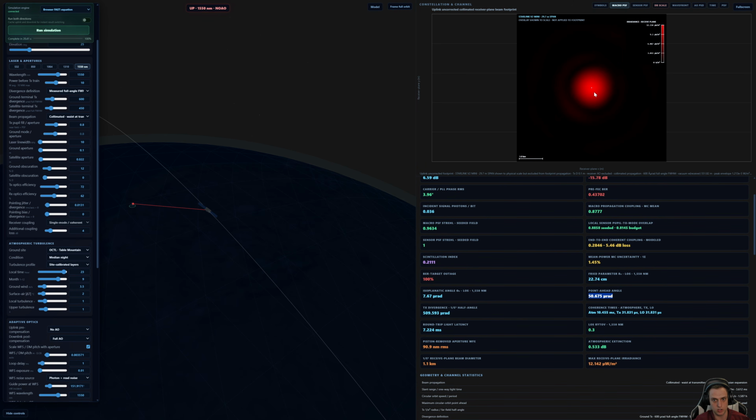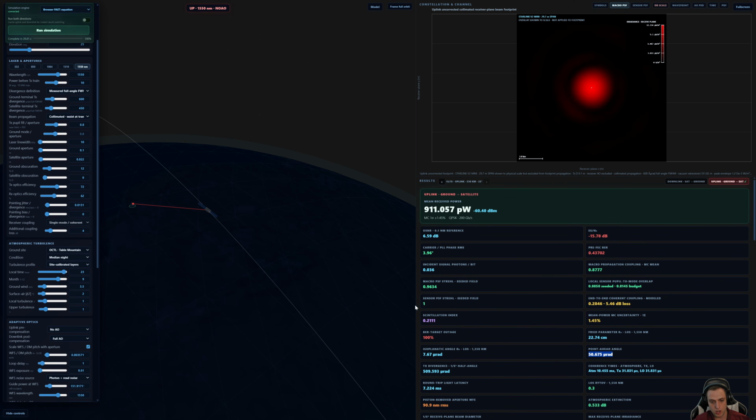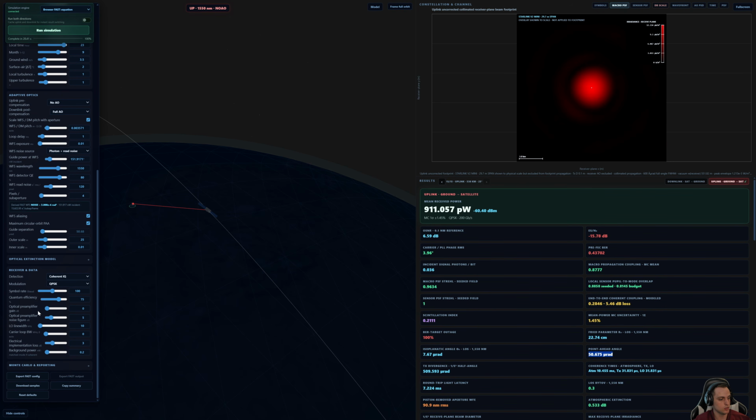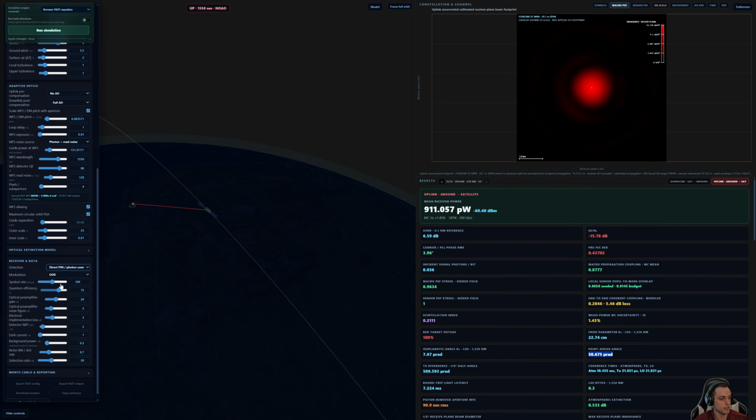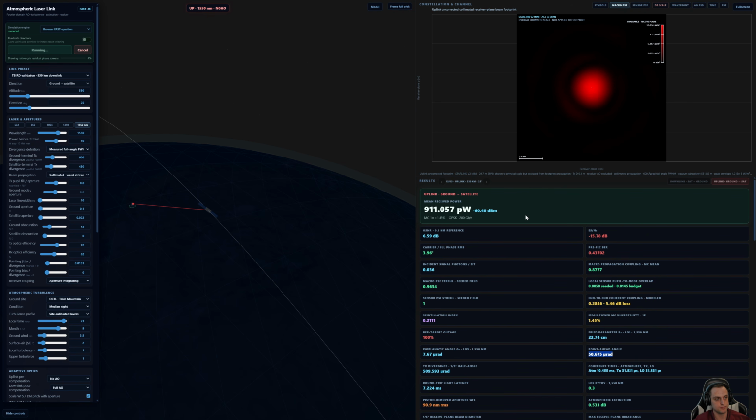And you can see this is 1 kilometer across, and the satellite is only moving a tiny fraction of that during this trip. The Strehl ratio, the coupling efficiency, those are all going to be relatively good. And actually, we're going to use direct detection with this anyway. And so let's just throw that in already, direct. Okay, and so the problem though is that both the transmit and receive have very low gain, very high divergence, and so the power received is going to be very low, and so you can't do a full 200 gigabit with these tiny aperture transmitter and receiver terminals.